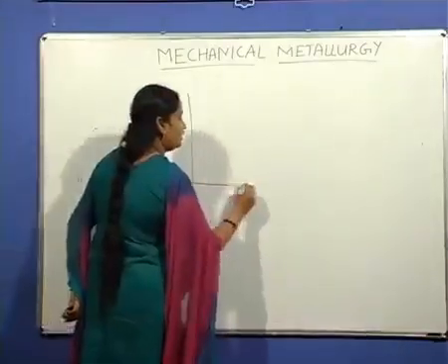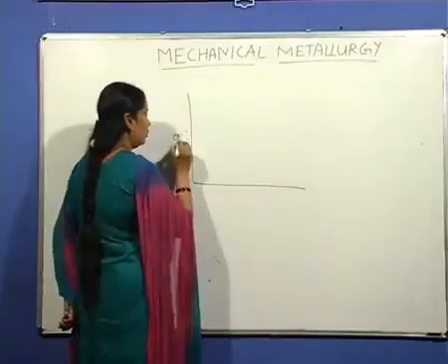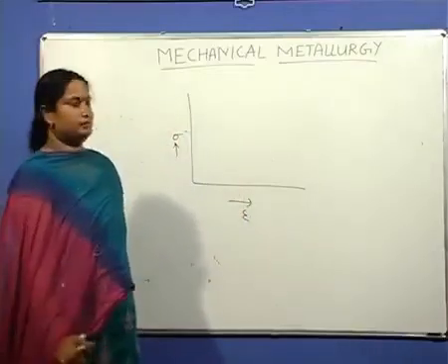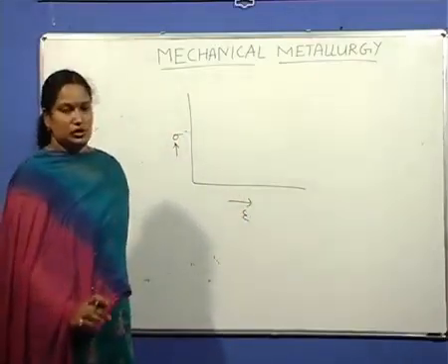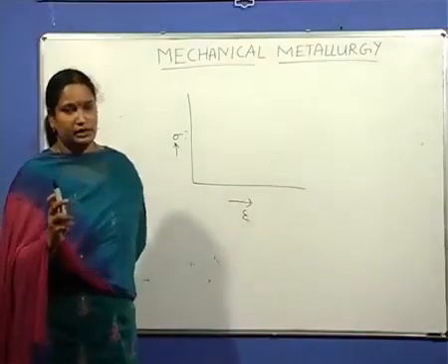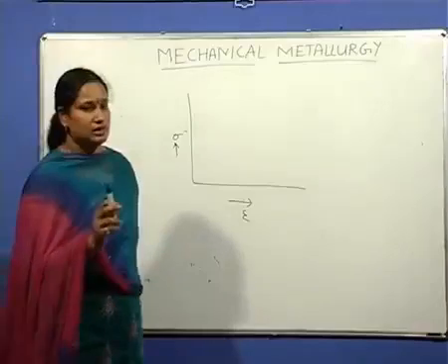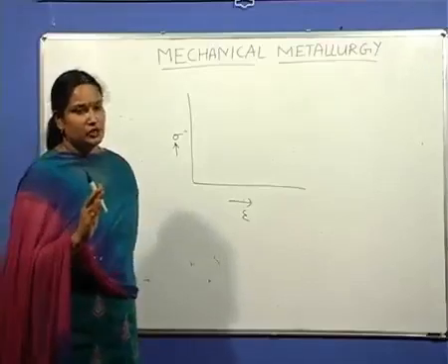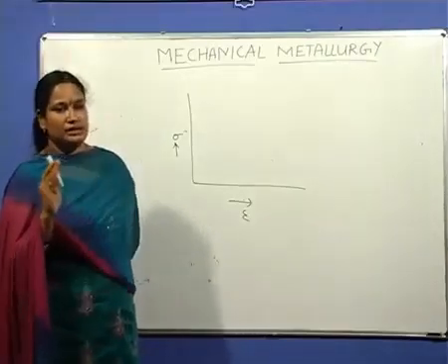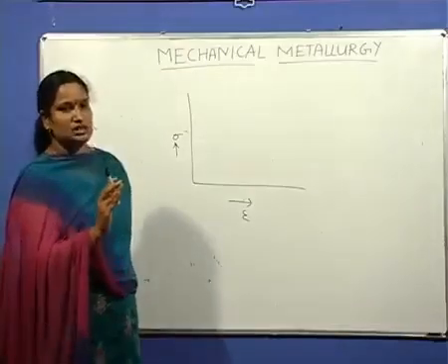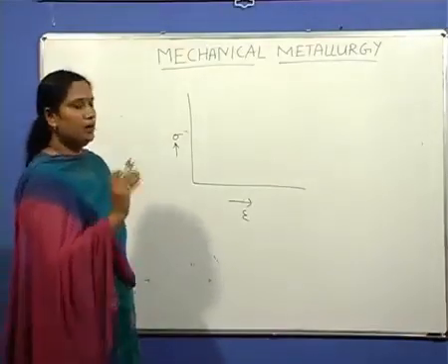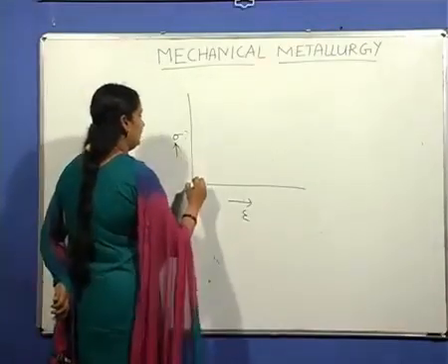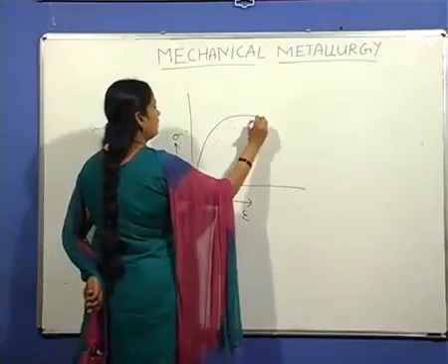Okay? So upon the conduction of tension test, a plot of stress versus strain is drawn. Stress versus strain is drawn because we know the geometry of the material, we know the load or force that is applied on the material, as well as what is the extension that is taking place, which is measured by means of an extensometer. So knowing all these things, you can find out stress versus strain, and then you can plot it. So the graph for a ductile material somewhat looked like this.